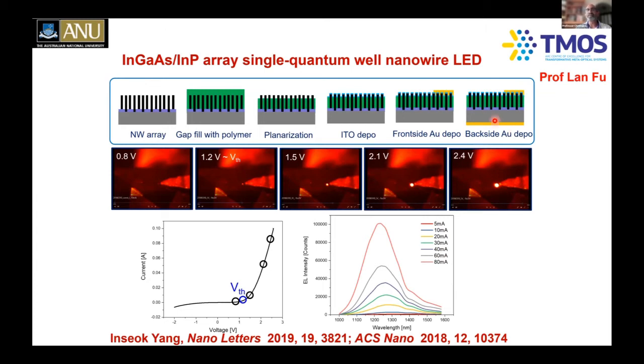One of the nice things with this one is that you are able to peel these things off. That means you can create foldable LEDs, because Samsung and Apple and others want to create foldable phones and foldable computers and other things. So that's why Yunusuk spent a lot of time developing these foldable or flexible LEDs, which we have really been able to do using the polymer embedded nanowire LEDs.